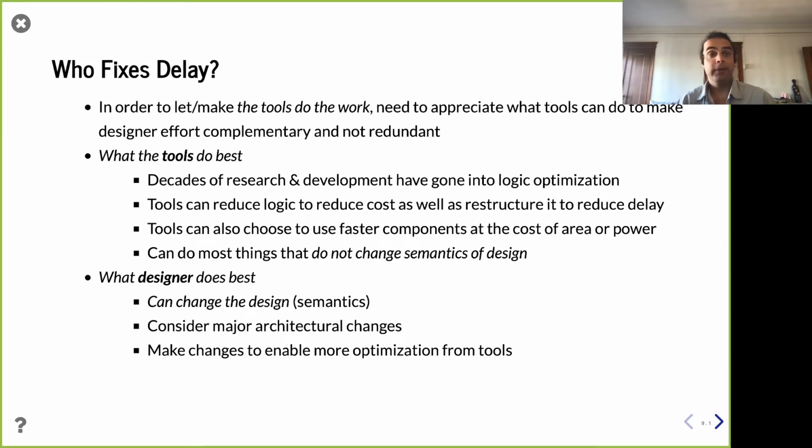So when you're writing your design, think about what's easiest for you to get correct, and easiest for you to make readable or modifiable, and let the tools worry about optimizing logic, right? They're going to do that pretty well. And they have a lot of choices that are perhaps invisible to you at the design level, right? Working at the RTL level, whether it be Verilog or Chisel, you're thinking, what's the logic operation I'm doing here? Understand that when these tools are optimizing, they have a lot of choices, right?